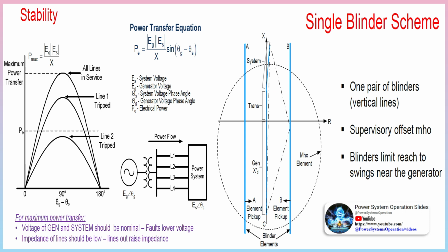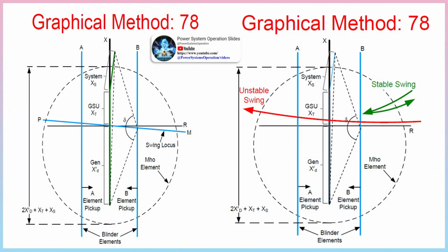Z3 may be used in conjunction with Z2 to form out-of-step blocking logic for security on power swings or to overreach remote bus for system fault backup protection. Load encroachment blinder provides security against high loads with long reach settings. Use minimum current supervision to provide security against loss of potential when the machine is offline.